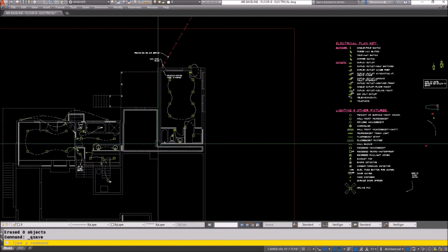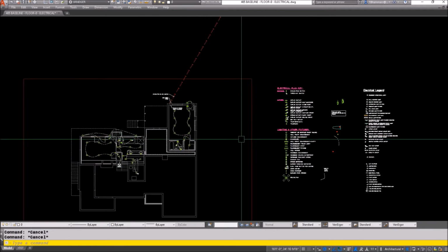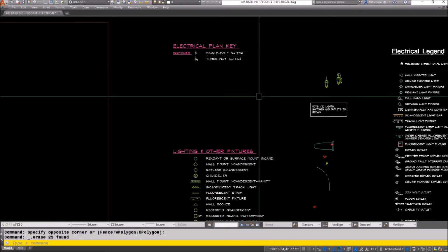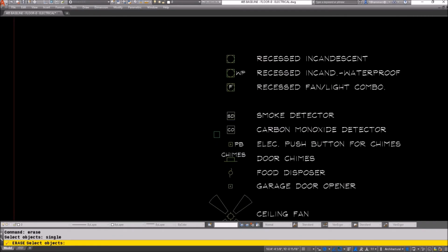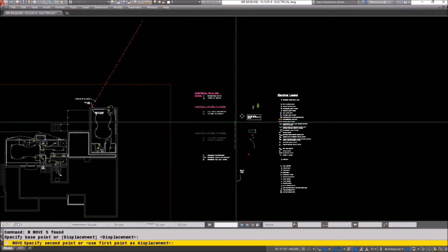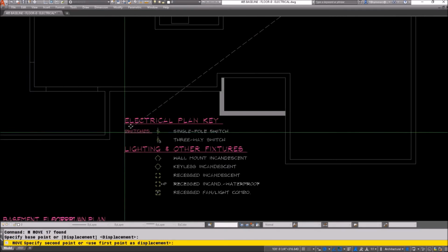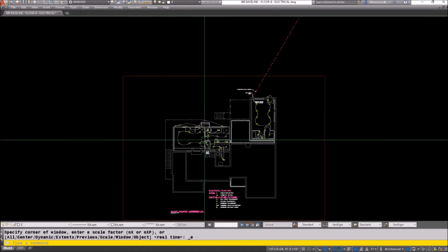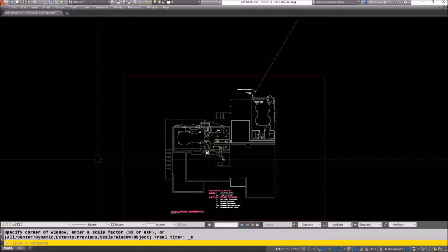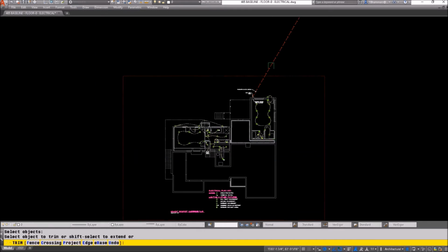Oh, by the way, I do have that set so that if I double click a line, I'll be drawing a line on the layer that line is on. Or if I double click a polyline, I'll be drawing a polyline on the layer the polyline is on. It's just so fast. It's huge acceleration. Instead of having to pick the line command, if you're in a drawing that already has geometry, this is a way to hyper-accelerate your work.